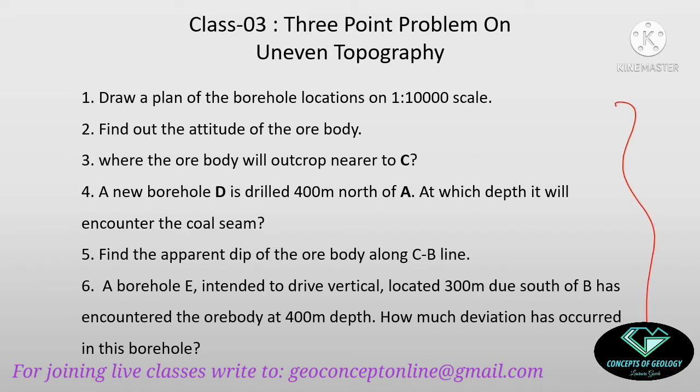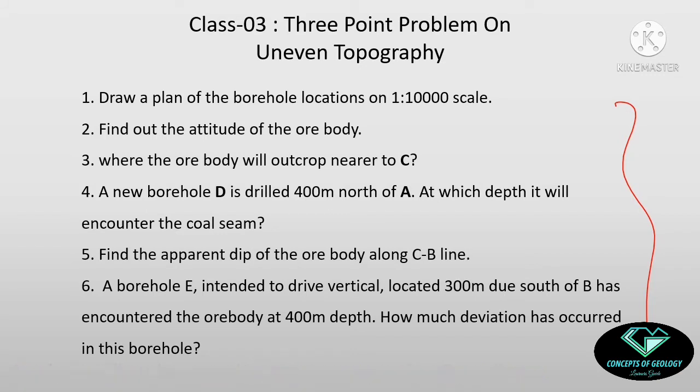First we need to draw a borehole location plan in 1:10,000 scale. Definitely 1:10,000 means 1 centimeter in my map will be 100 meter on the real ground. After that we need to find out the attitude of the ore body, and with that we have some more questions which we will gradually move on and try to solve.